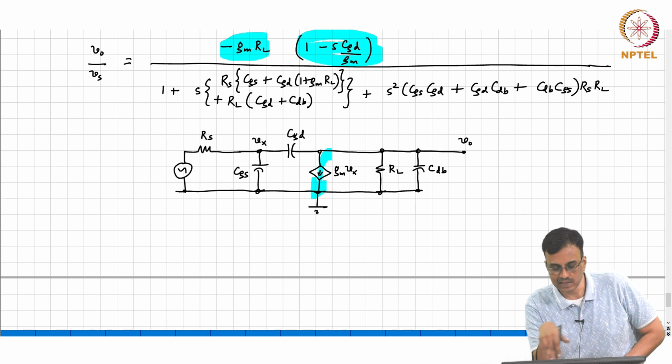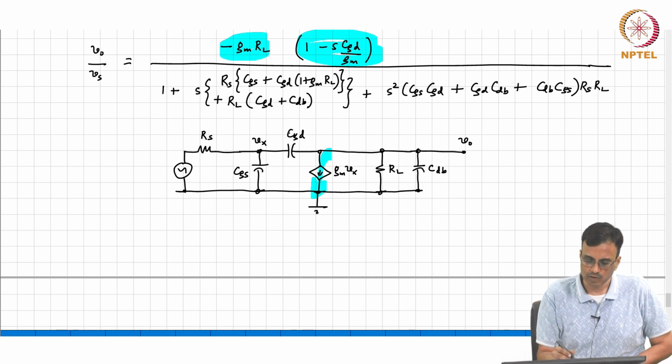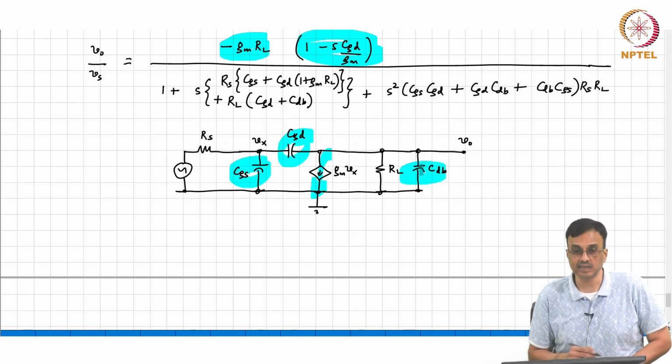So you have various elements in this network. You have capacitors, resistors, and so on, right? At DC, all the current is flowing in the elements in the branches whose behavior is frequency independent, right? As you keep increasing frequency, what happens? Yeah. So basically, as frequency keeps increasing, these capacitors which are open at DC start to draw current, right?